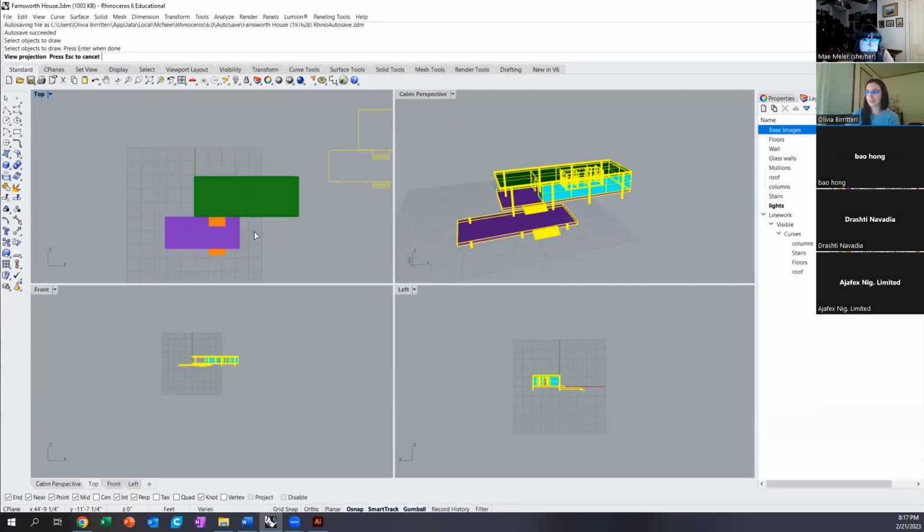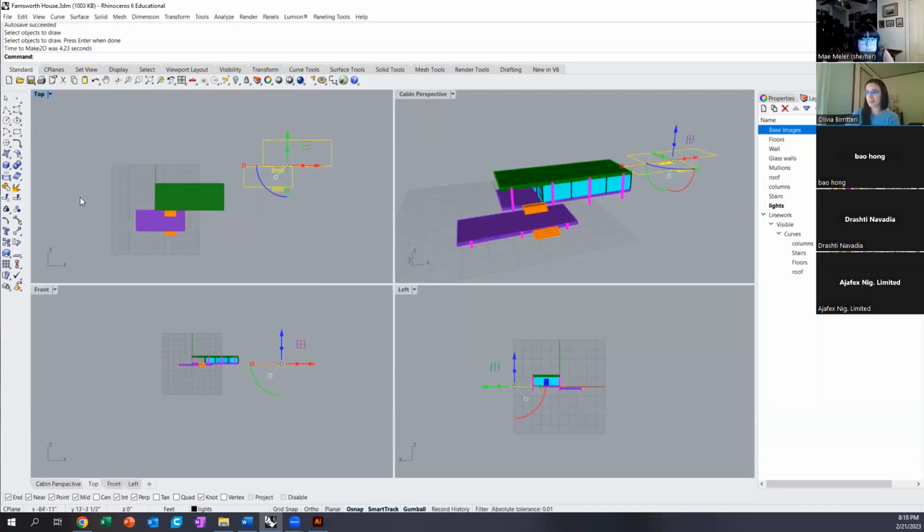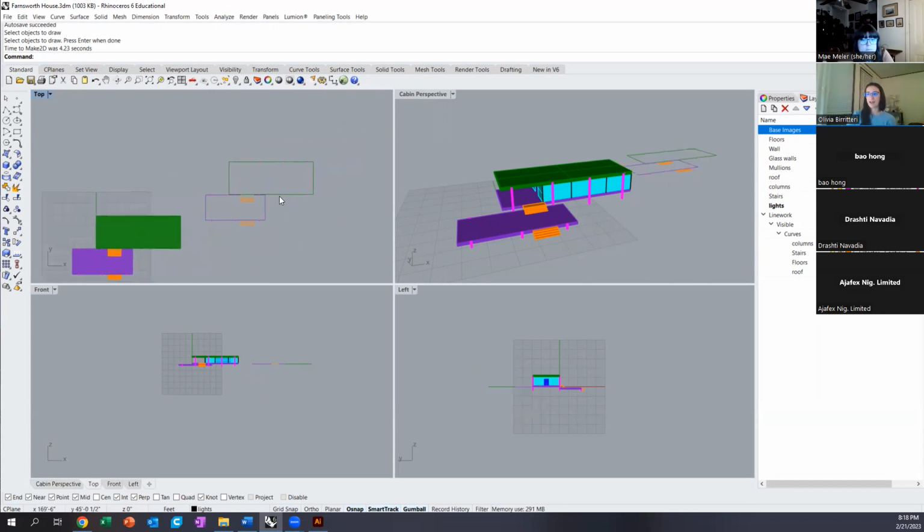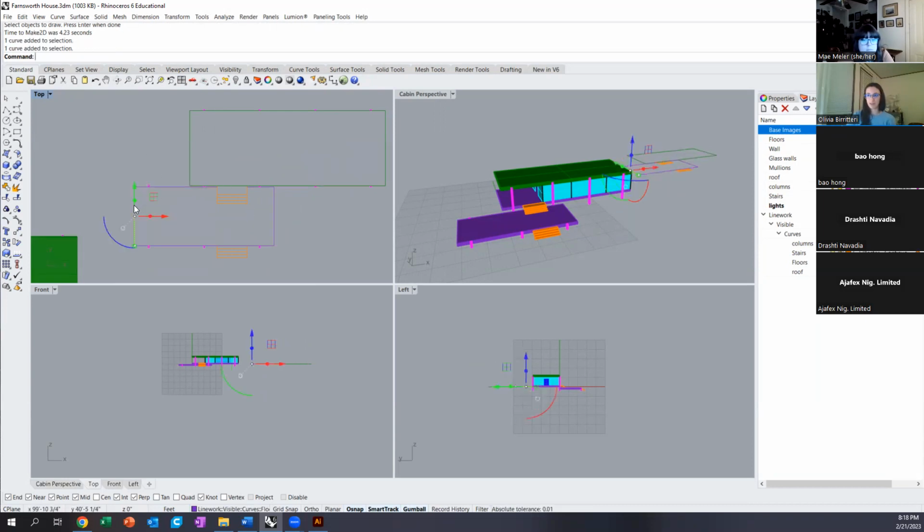it's going to think a little bit. It's generating some lines. Just by typing Make2D and selecting that view, you see here, I have already created a roof plan. So I haven't had to draw any of these lines myself. It just took what info it saw in Rhino and extracted that into